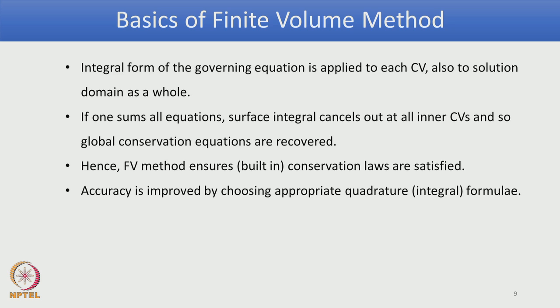And in the case of finite volume, one more point we have to note, as I mentioned before: though it is an integral over the surface, we have different quantities, one is the convection flux, the other is the diffusion flux, and they may need to be treated separately for some problems, or they may be treated the same in other problems, or in the same domain they may be treated the same or differently depending on the nature of the solution within that problem description. So, accuracy is improved by choosing an appropriate integral formula or quadrature formula which approximates the expression in the integral equation.